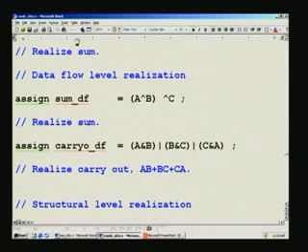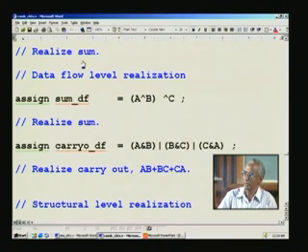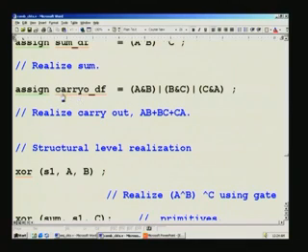And notice that as an example, in order to show all these features, I have interconnected them, using the very same inputs, outputs as far as possible. Only the outputs have been changed, as I mentioned before, because 2 results will be contradictory. It will take the latest and overwrite the previous result. That is why the name has been changed in some cases. In this carry etc., I had used the very same name. Now, I have marked the difference here. See, I have just extended carry out underscore df. It is to connect it to data flow, because that is what we are dealing with here.